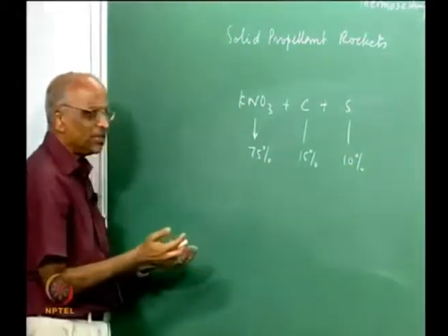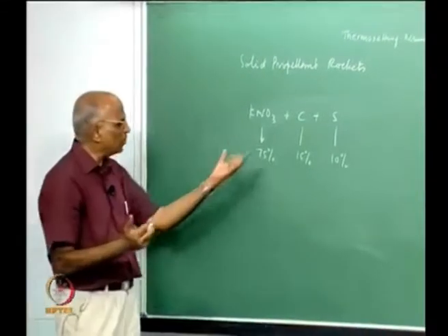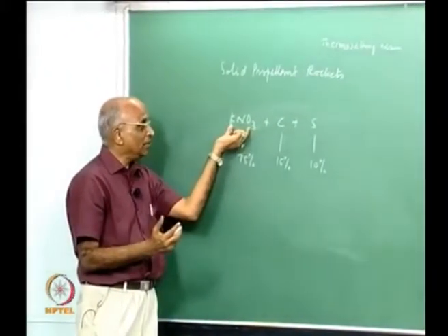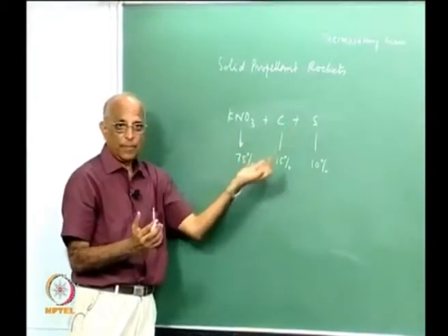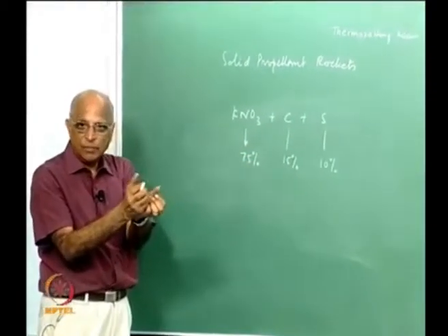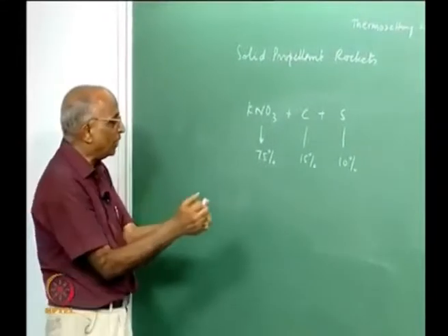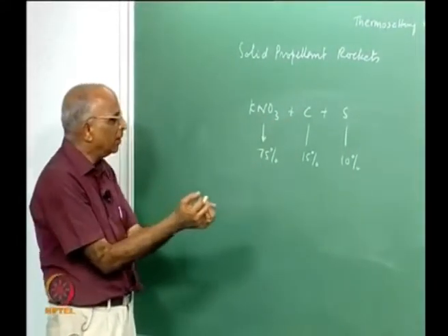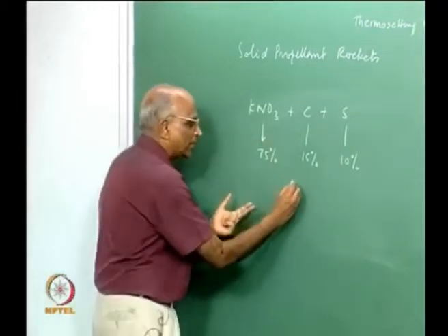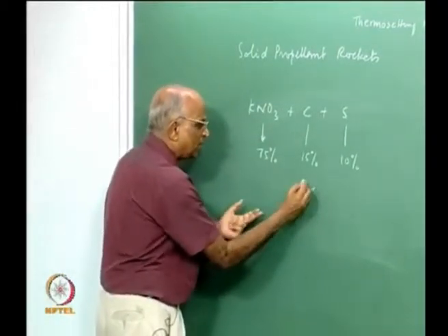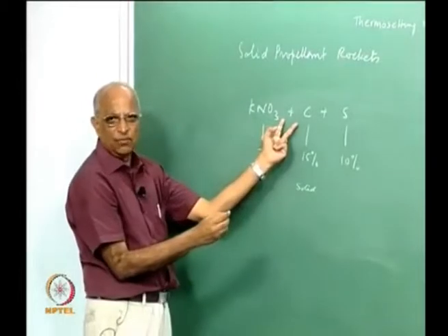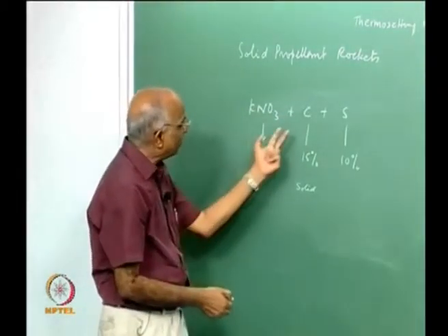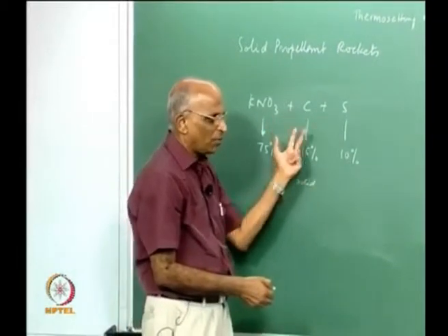And how do you form these crackers or sparklers which use this black powder? You have these solids, an oxidizer and fuel, you grind them together, maybe make a good mixture of it, maybe add some glue, in which case it becomes wet, you cure it, make it a solid, and that is what constitutes a composition. Well, this is also a composite propellant. Therefore, let us take the example just to understand a little bit further about burn rate.